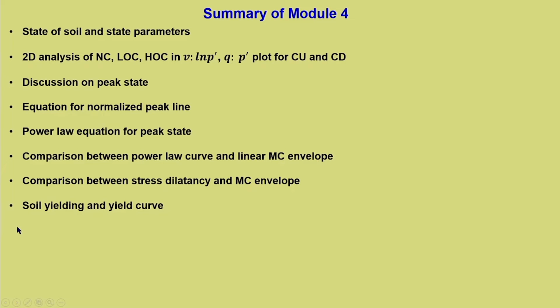Then a very important concept of soil yielding and yield curve was discussed. Without this, the explanation is not complete, and that is where this course is different from the UG concepts you have learned. The strength and the failure, those things we could still conceive from our undergraduate background, but adding these points like the yield curve and interpretation of the results with respect to the yield curve, and how it fails from the elastoplastic state from where it starts. These things were slightly additional in this particular course.